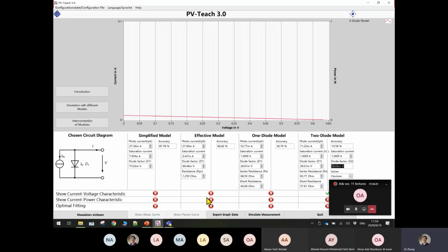So you can see here, besides plotting the IV characteristic from the model, we can also import a certain measurement of our own. If you have your own measurement, you can import your data into here. And then what you can do next is fitting. You can try to use your model here to fit to the actual experimental measurement that you have, maybe a text file, maybe an Excel sheet, you can import into here. I think this is not exactly English, but this button will let you import your measurement data, and then after that you can do the fitting.